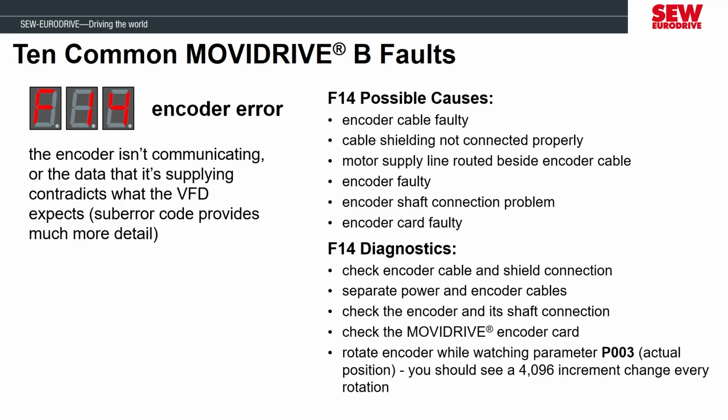However, if you have a servo motor with a resolver, you should never remove it for troubleshooting, since it has a specific angle alignment that is done during assembly. If you have a servo that the encoder or resolver has been removed for troubleshooting, you will need to contact your local SCW office for support to get the encoder or resolver realigned to the motor shaft angle.